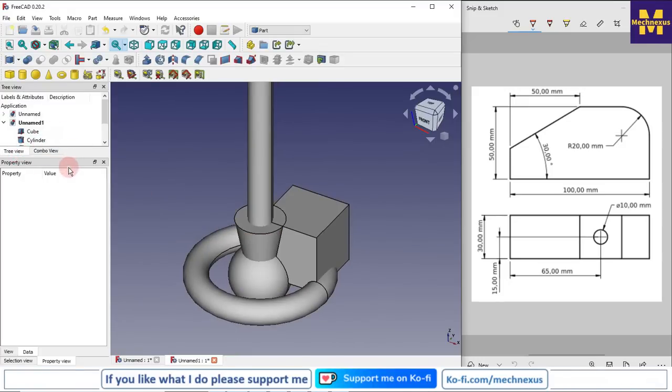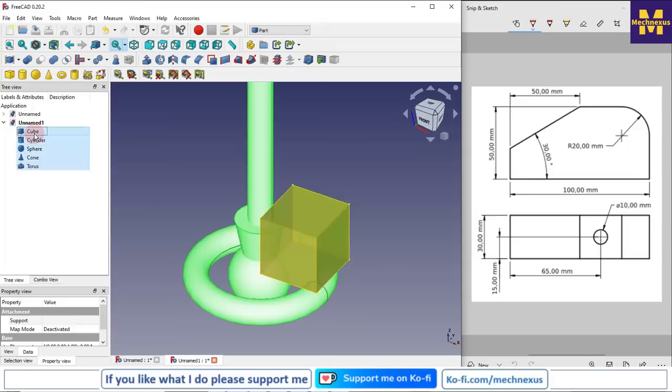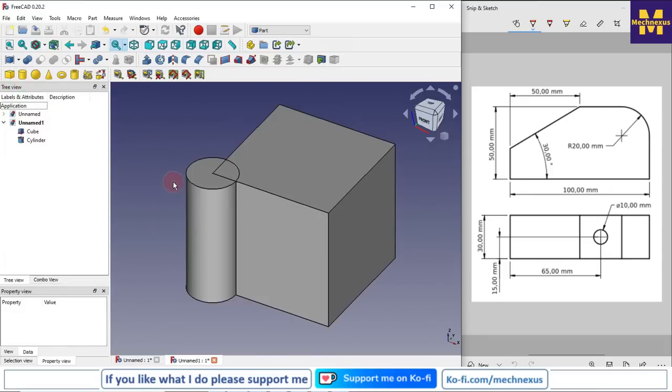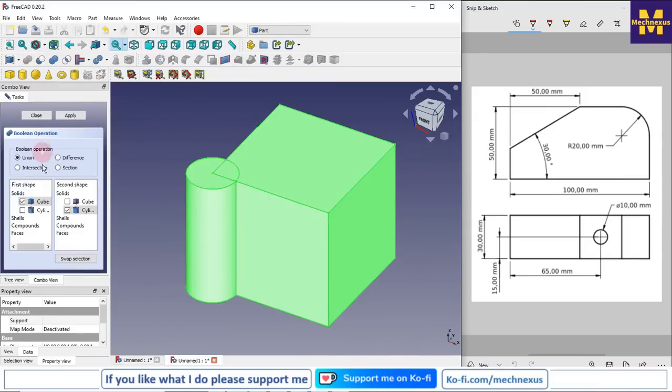Now we will learn the Boolean operations in FreeCAD. So I clear all this. For the Boolean operations, I will simply select a cube and then a cylinder. First I select my cube and cylinder and click on this Boolean operation.